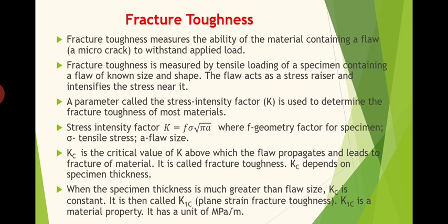Why that word is added is, see, if a micro crack is introduced or is there within the material, of course stress concentration is going to be happening there. So because of that stress concentration, even though we are applying only a very small stress on the material, at that stress concentration region, a much higher magnitude stress is going to be acting. So the material will of course fail because of that high stress acting at the tip of that micro crack.